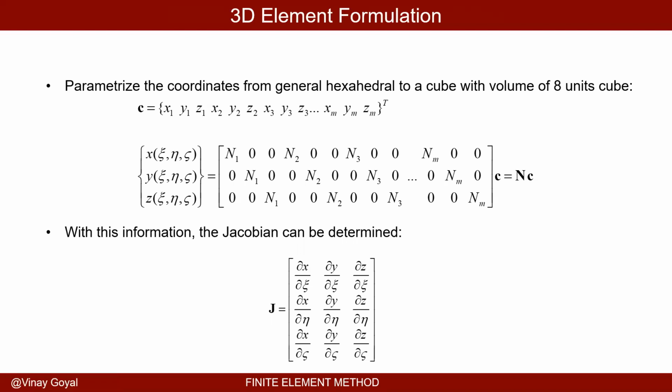And that's fairly simple to deal with. I know those values. I know the shape functions for every element because they're going to be the same in the natural coordinate system, and I'll discuss what they look like for a cube. But generally speaking, that's the process, and I know how to do that in a very simple way.